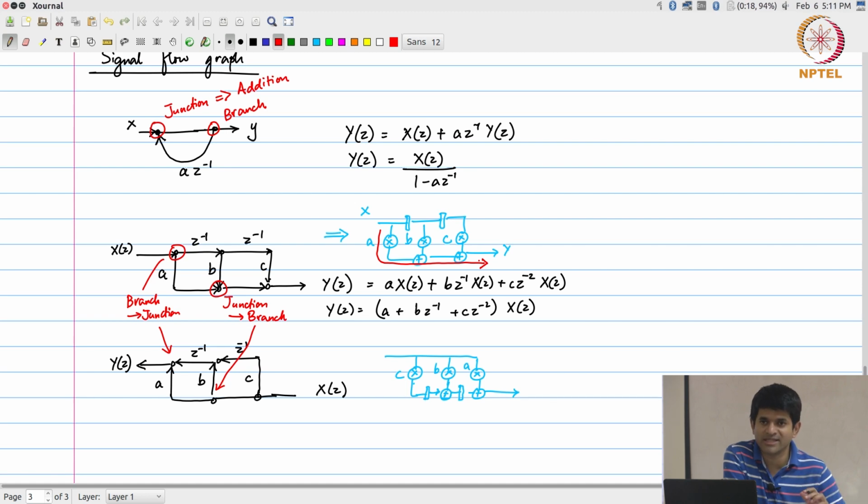Yeah, there are a lot of optimizations you can do. But at the end of the day, there are a whole lot of adders that are going to end up in your critical path. Whereas over here, the critical path is essentially going to be always 1 multiply and 1 add.